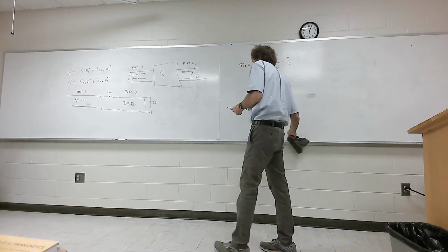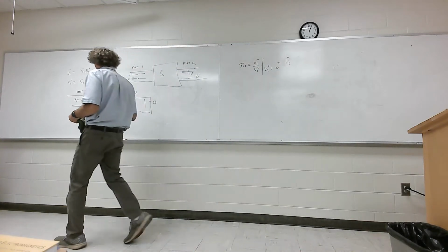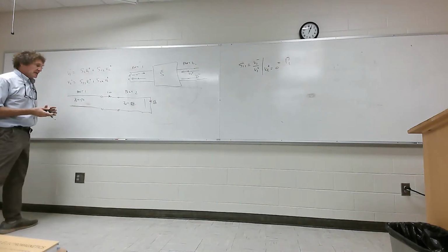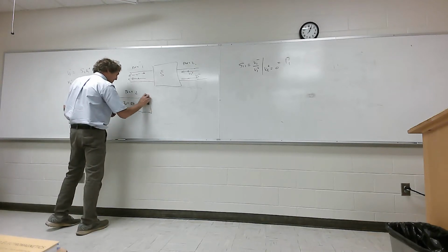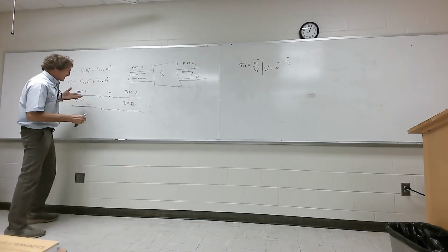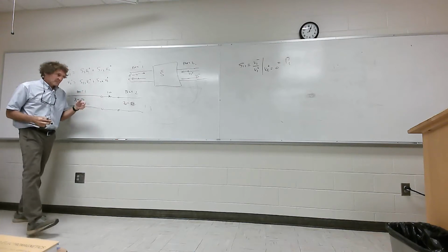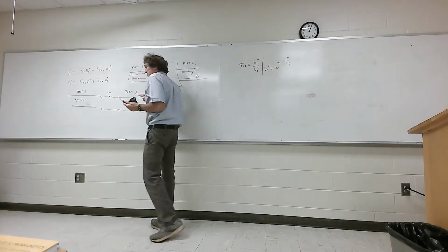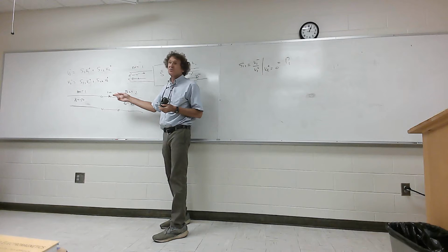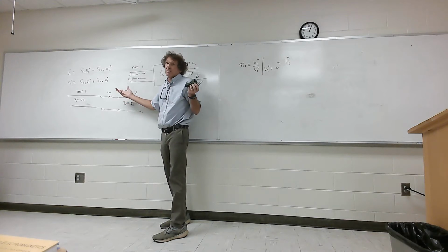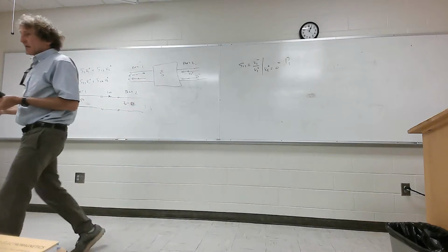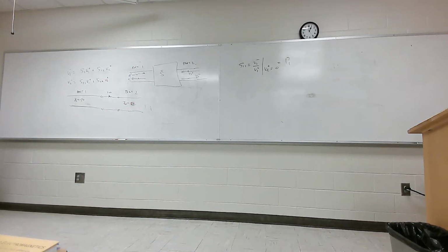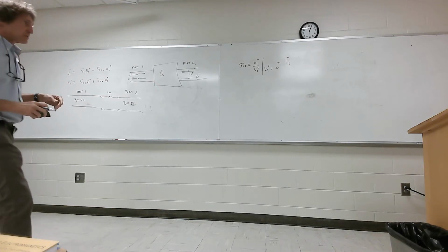All right, so looking at this, now I'm going to get the effective, and by the way, this is a symmetric network. By that I mean that if you look at it this way, it is identical to the way it looks this way. You all follow me? It means you only have to find half the parameters. You got the other two. S11 will be S22, and S21 will be S12. All right? Follow me on the thoughts on that? This would be called a reciprocal network, by the way.